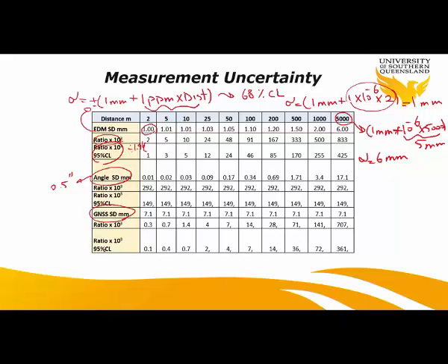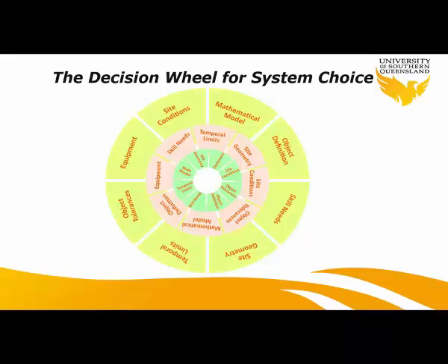The GNSS is a little bit different. GNSS is the error introduced by each station, so it's plus and minus 5 millimeter per station. To measure the distance, we always have 2 stations, so using the error propagation formula, we get roughly 7.1 millimeter uncertainty in the distance. So you see that GNSS accuracy is not changing over the distance because it's irrelevant.